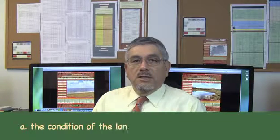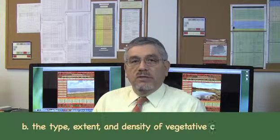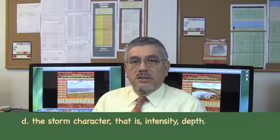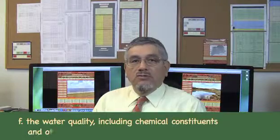Infiltration rates vary as a function of A. The condition of the land surface or crust. B. The type, extent, and density of vegetative cover. C. The physical properties of the soil, including grain size and gradation. D. The storm character, that is, intensity, depth, and duration. E. The water temperature. F. The water quality, including chemical constituents and other impurities. In general, infiltration varies as a function of the physical, chemical, and biological properties of the soil mass.